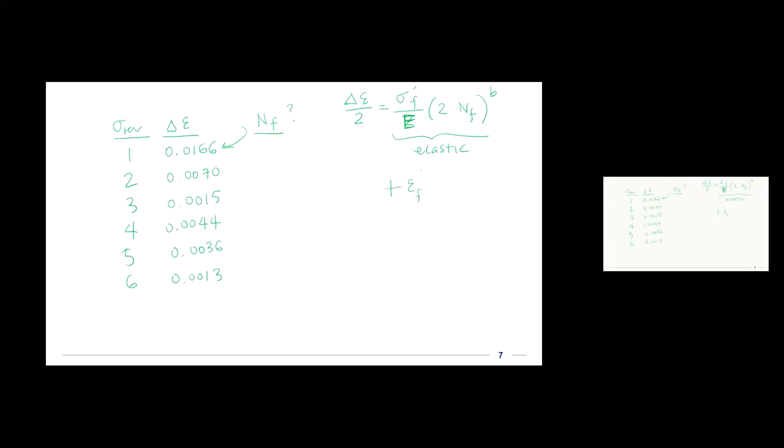So we have a coefficient, the fatigue strain to failure in low cycle fatigue, epsilon F prime. Then we have our variable, 2 times N_F, put to the C power. That represents the plastic portion. So you can see now that we have a function where strain corresponds to the number of cycles to failure.